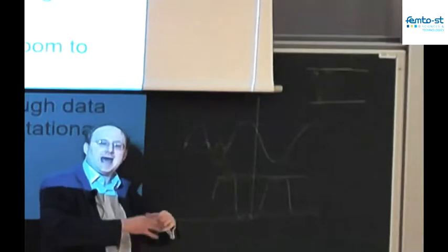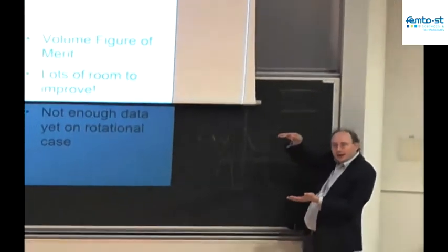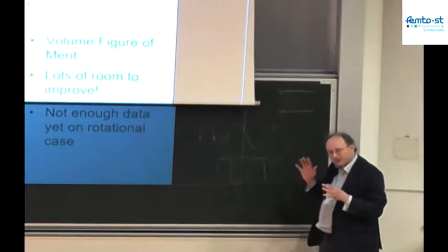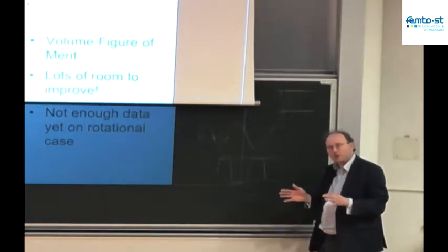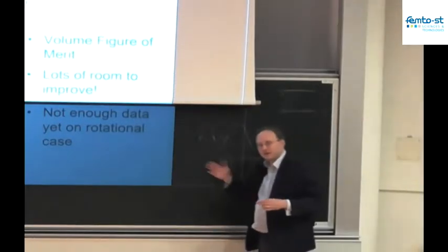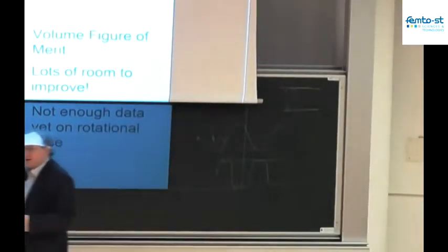I can take my fundamental displacement waveform here and a fundamental force. I can then add some harmonics into the displacement waveform, allowing me to pull down the overall displacement, but then maximize again and increase the fundamental value in order to get a little bit more power. And assuming still that I'm exciting the device with a pure harmonic tone, the additional harmonics here simply don't matter. A little bit of energy sloshes around, but it doesn't really affect the real power that you can generate.